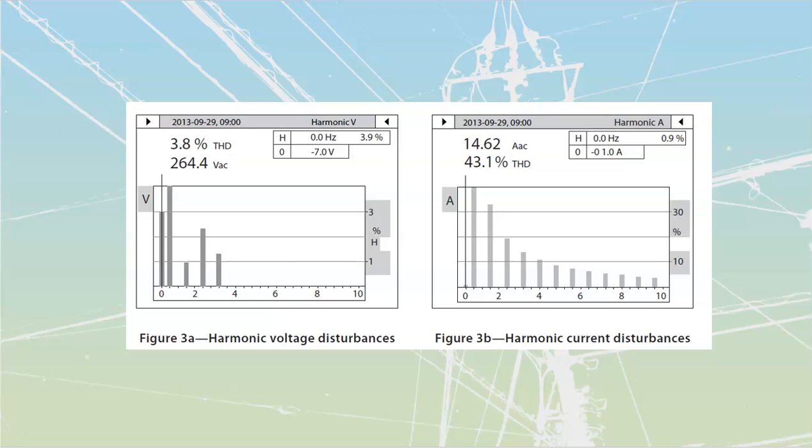You're going to have dedicated feeder cables where necessary so that you don't share harmonics. If you've got a huge VFD, it's better to run out a separate cable for that rather than go into a small sub-electrical room and feed a bunch of other stuff off of it. Make sure your neutrals are large enough. Make sure that when you are dealing with conduits, you're not just relying on the conduits themselves to carry all of that bond current back. Okay, make sure you put the insulated bond conductors inside, etc.